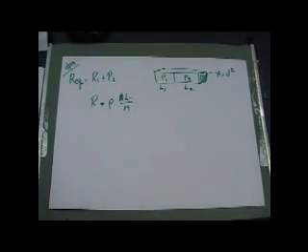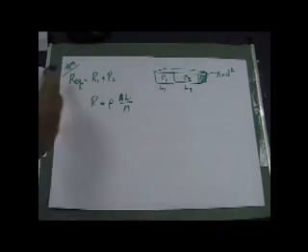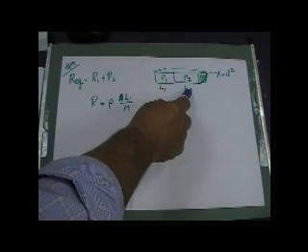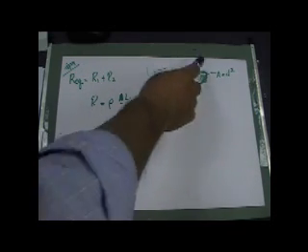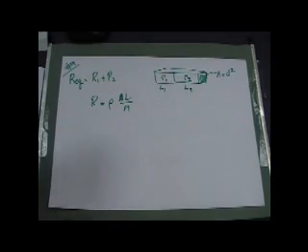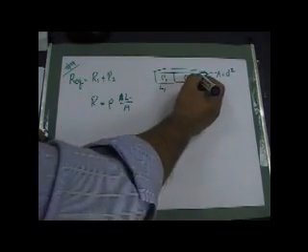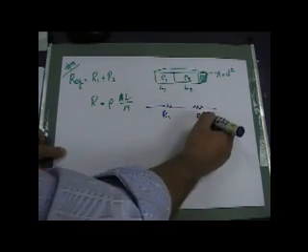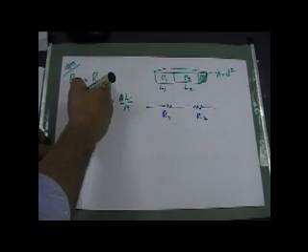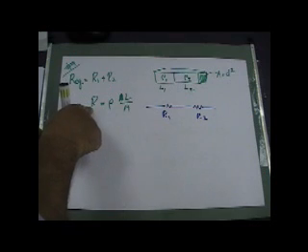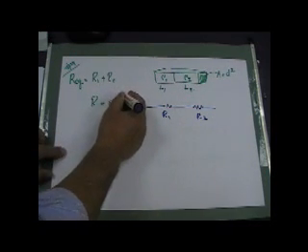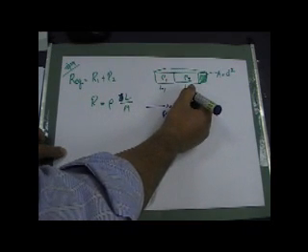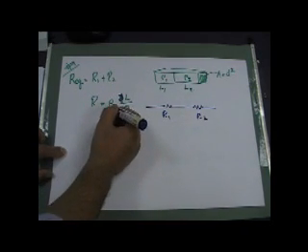Okay, question number 9, we have a rod made up of 2 materials, rho 1 and rho 2, with lengths L1 and L2, and they have the same cross-sectional area. He wants the resistance between the 2 ends of the rod, so basically he wants R equivalent. If this is R1 and R2, the equivalent resistance will simply be R1 plus R2, and each one of them is R equals rho L divided by A. L in each one is L1, L2. The area is the same, and rho is different.